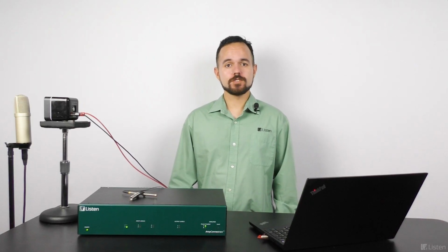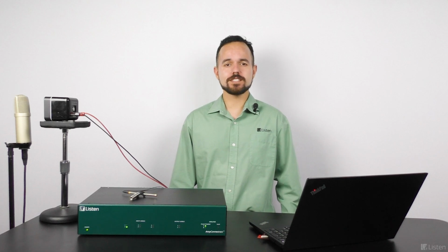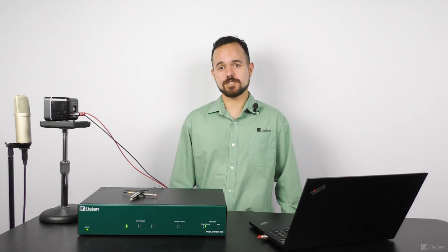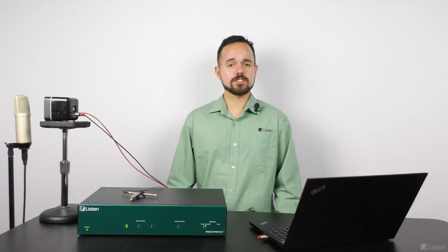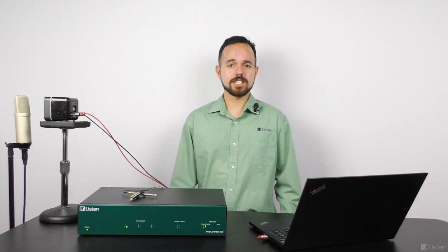So there you have it. Two simple methods for measuring microphones that ensure any non-linearities in your speaker don't affect the measurement. And of course, these are some of the most basic microphone measurements that you can do in SoundCheck. We can also measure directional response, acoustic overload point, signal to noise ratio, embedded mics, MEMS mics, and more.